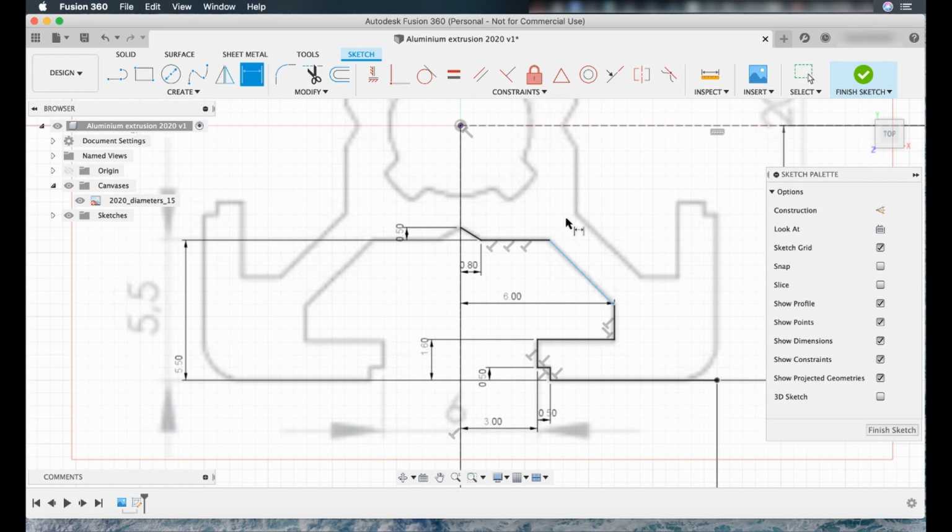So I just leave it like this, and I escape from this editing now, click escape, and I will add another construction line between this point and mirror the whole line we drew around this line. So I will make a construction line, so I click this one and I hit L for line tool again, select the center and select this endpoint here. So now we have this dashed construction line here, click escape.